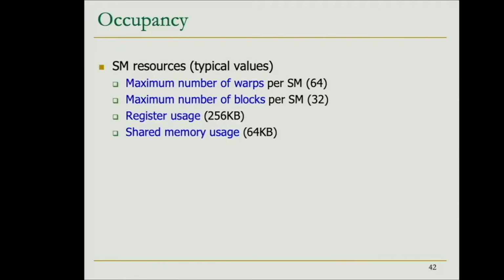Also observe that this occupancy, which you had the definition of in the previous slide, is the percentage of active threads, active warps that we have. This occupancy for the same program might also change depending on the actual platform. Why is that? Because if you compare different generations of GPUs, you will see that these numbers have changed a little bit over time, typically increasing, right? That's for sure.